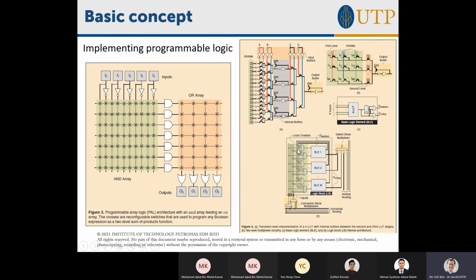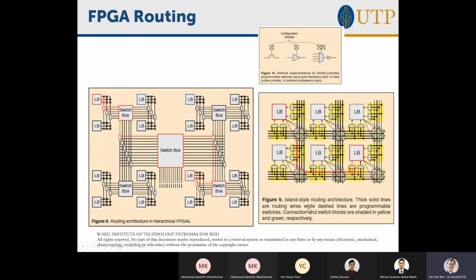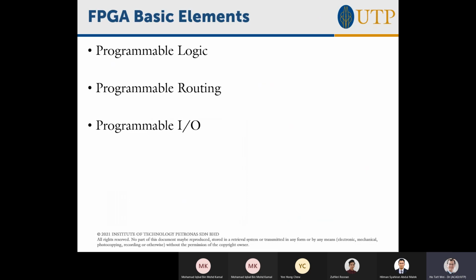So you are programming functions of the inputs going into the basic logic element. You are programming the logic function that's implemented in the basic logic element, and you are also programming which of these outputs is actually being sent to which output lines. And there are a bunch of these configurable logic blocks put throughout the FPGA. So that is the basic structure of an FPGA.